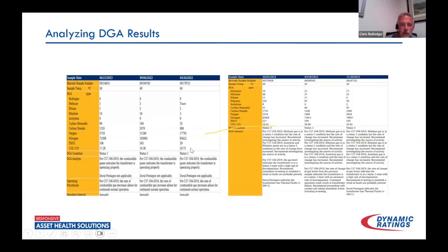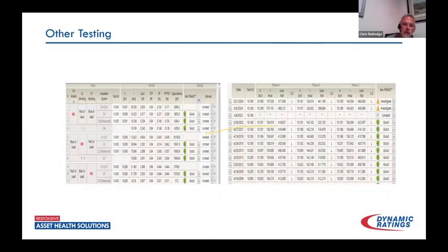But if we look at our carbon dioxide ratio over this event, 20.73, 14.3, 17, 20, 38, 34. So not going down, pretty much staying, even going up a little bit. So right off the jump, we know we have an event occurring that's somewhere in that 700 degree C range. It doesn't appear to be affecting the solid insulation system so much. So we know this is the LTC type transformer. So now we need to do some more testing to kind of determine what's going on.